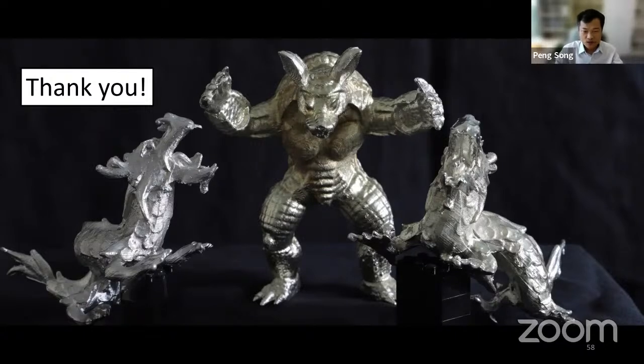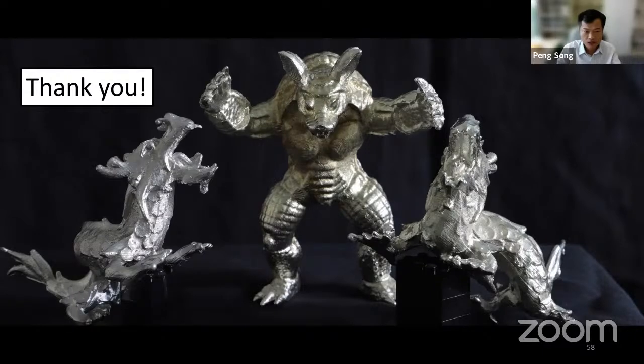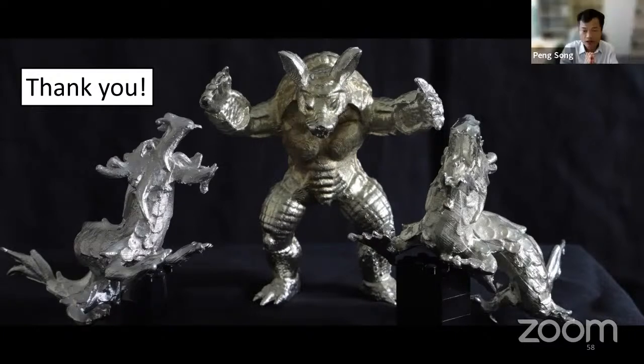Okay. So in your composite mold, you have this flexible part, and you create some cuts on the flexible part for taking the object out from the mold. I'm just wondering about the criteria for creating these cuts. For example, do you want to minimize the number of cuts? Because I guess they may create some artifacts on the fabricated objects, because there is a gap. Every cut will correspond to a gap, and the material may go inside the gap.